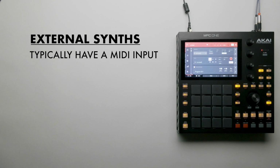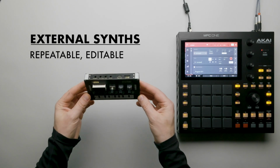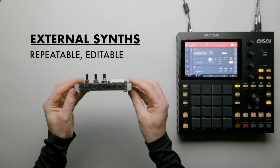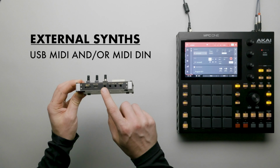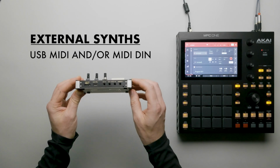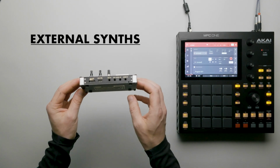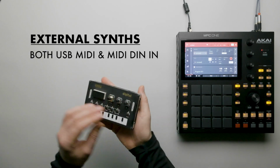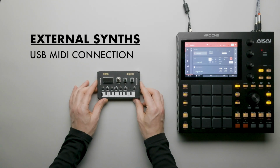Most synthesizers have a MIDI input to allow for control from an external device like the MPC. This is beneficial because we can program a sequence, edit the notes, and make it repeat exactly the same every time. As we mentioned previously, MIDI can communicate over USB and MIDI DIN. Some synths have both, and some have one or the other. Here we have a Korg NTS1 synthesizer, which happens to have both MIDI in and USB MIDI. Let's show you how to connect each type, starting with USB.